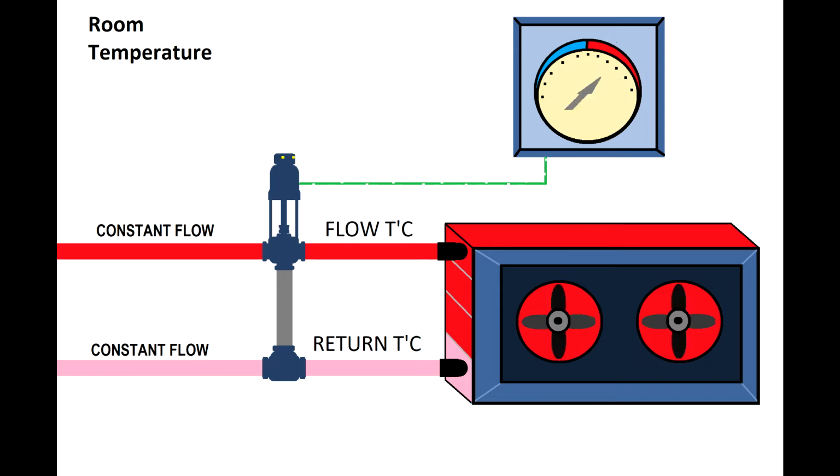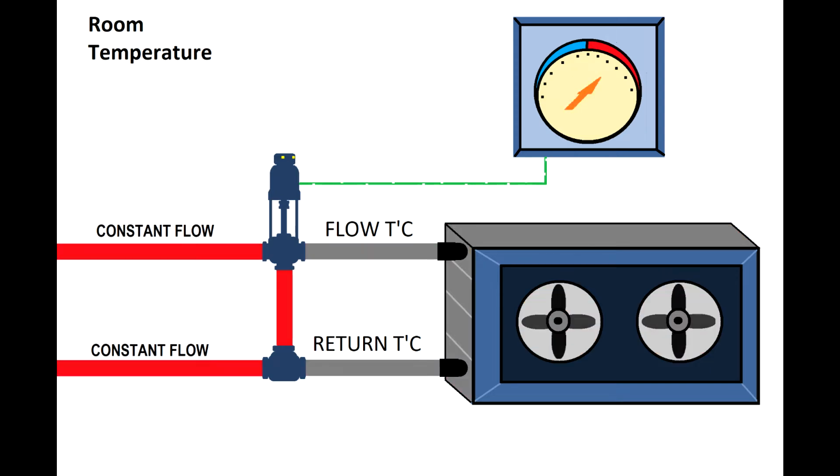It's a very basic system. Just like I said, when the temperature is satisfied, the thermostat will instruct the actuator to close the valve that allows the heating agent to pass through the heat exchanger. In that case, the premises will slowly cool down, and when the thermostat senses that the temperature is too low, it will enable the valve again, and the heating agent will pass to the heat exchanger.